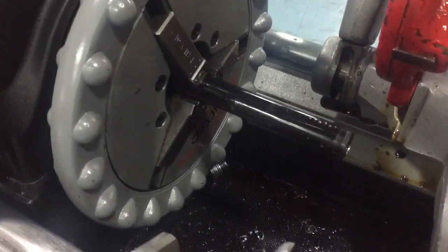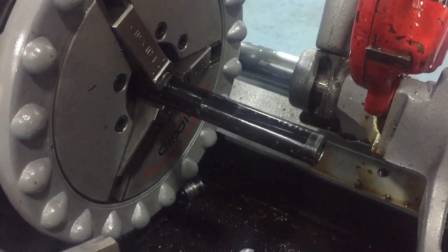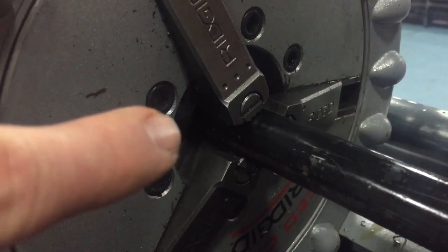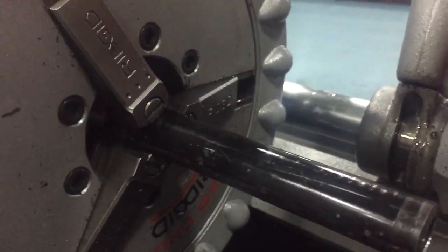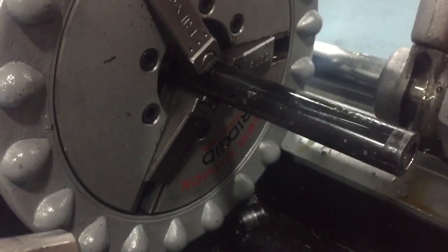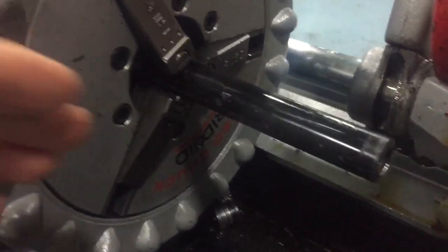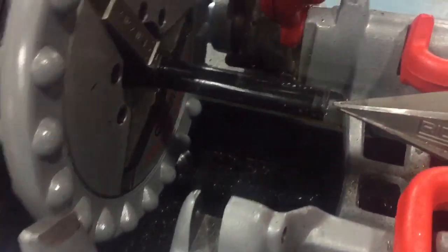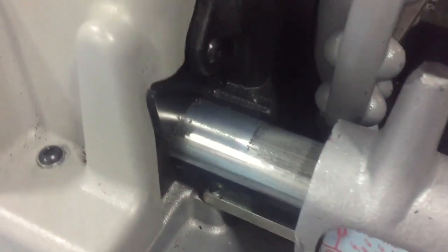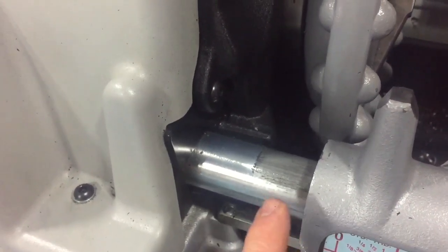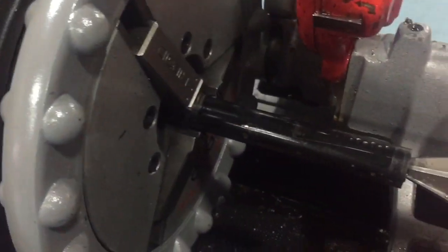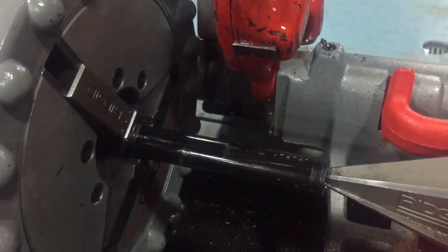All right, so when we flipped our 6 3/4 inch pipe around here, and just to note, I don't know if you can see it back in there, you can kind of see the threads. We want to make sure that our chuck isn't biting down on those. So there's kind of a minimum length that we can do here. We're pretty close to it, but we want to make sure we have this out as far as we can, so when we do bring down the reamer here, that it doesn't, if you look here, the tools here only can slide to about here. So looks like we'll be good still, but just take note of the positioning of this pipe here, you need to ensure you have enough out here so that the reamer will actually function.